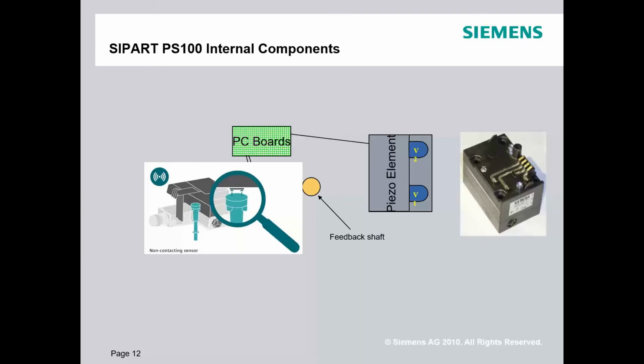What it does when you calibrate is draw something called a valve signature. All valves are a little bit different, and I don't care how linear somebody says their stuff is, it's not perfect, but that's okay. It looks at that and says, okay, this is what we want from now on.